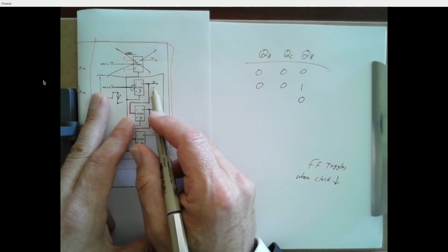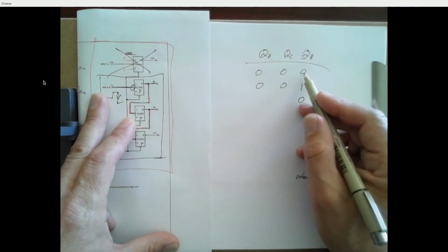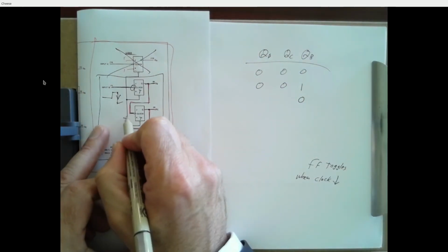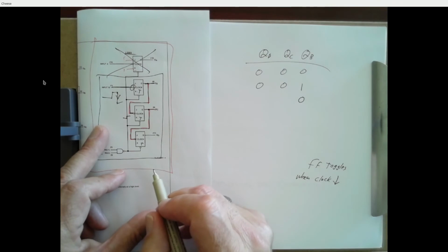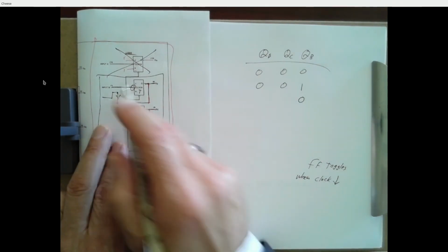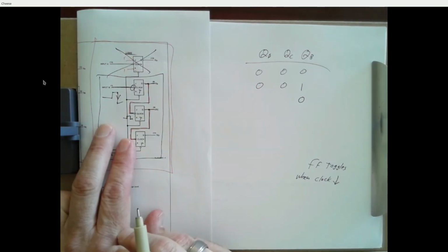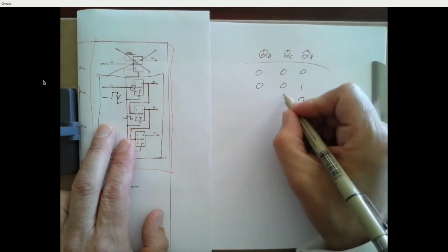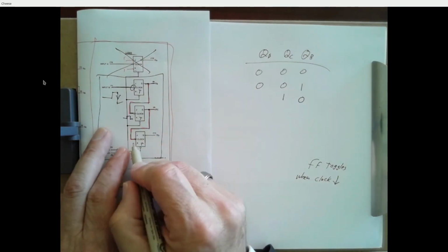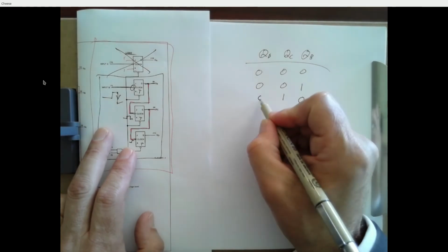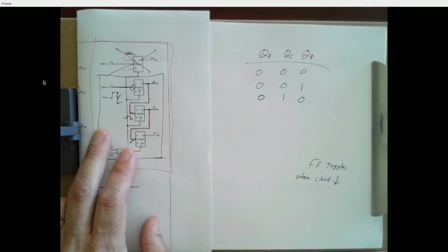So in this first row, QB was 0, this input B, the clock ticked, QB changed to a 1. So this clock input changed from a 0 to a 1. Doesn't do anything. Right. But now we drop this input B again, QB changes from 1 to a 0. So now this clock is going from 1 to a 0. So what happens there? QC changes into a 1. And that changes this clock to go from 0 to 1. But that doesn't affect anything, right? Because this is all negative edge triggered, so this is going to stay a 0. But now it's counted to 2.